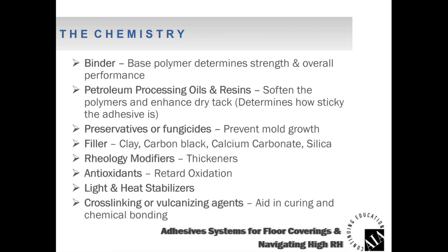There are also antioxidants in there as well. These materials retard the natural oxidation process, so those antioxidants can help extend the life of adhesives. With some of the adhesives out there, maybe the latex ones, you may see a 1-year adhesive, a 5-year adhesive, maybe even a 10-year adhesive. And in addition to the binders used in those adhesives, antioxidants play a role in the length of the warranty life of that adhesive.